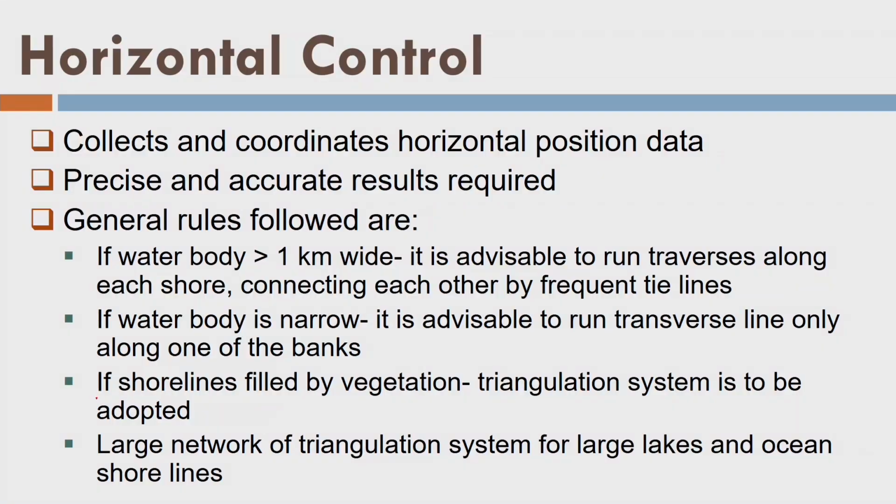But if the width of the water body is less than 1 kilometer, in that case we recommend that you start your survey, the horizontal positioning basically, from one shoreline only. One more thing here: if the shoreline is filled by vegetation, then a triangulation system should be adopted. At the same time, a large network of triangulation system should be adopted for large lake and ocean shorelines.